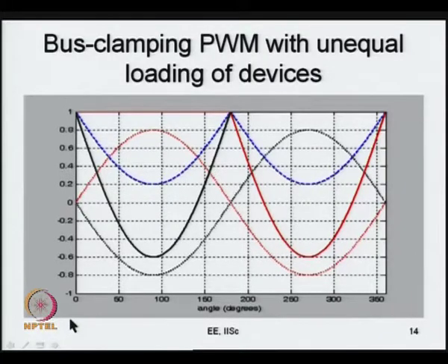Okay. So, it can reduce the switching loss, but is it desirable? There is something that you have to observe now. You see that the top device is conducting here, and in the second half both the top and the bottom devices could be conducting. So, you see that the top device is conducting for longer time than the bottom device in the A phase leg. The same way in the B phase leg, in this entire half cycle the top device is conducting, whereas in this half both top and bottom are conducting. So, overall again in the B phase the top device is going to be conducting now.